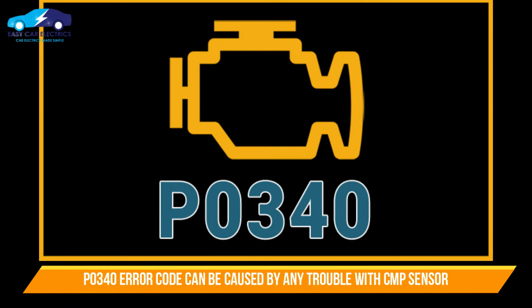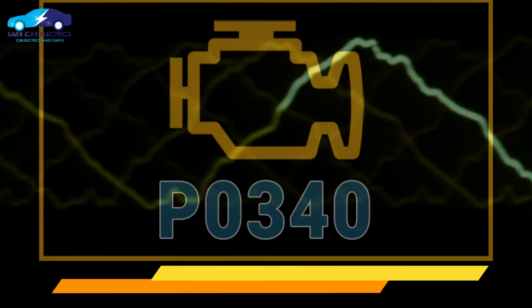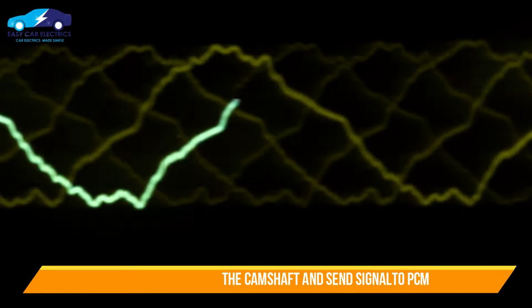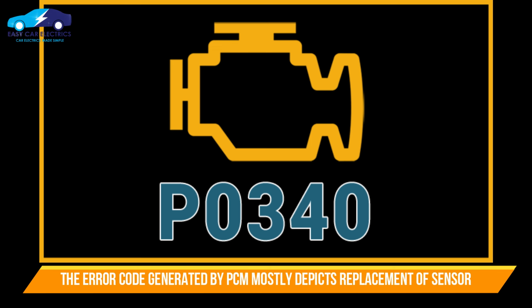P0340 code can be caused by any problem with the camshaft position, CMP, sensor circuit. This sensor is responsible for monitoring the position of the camshaft and relaying that information to the vehicle's powertrain control module, PCM. If the PCM detects an issue with the camshaft position sensor, it will trigger the P0340 trouble code, which mostly depicts camshaft position sensor replacement.